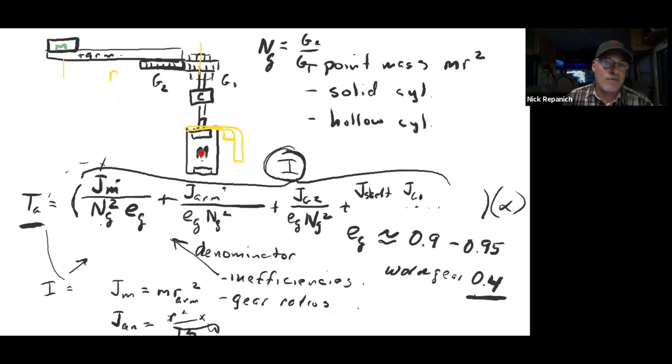They're all direct drive terms. That's nice for your formula, but that's actually bad for the motor, the overall system, because these things got reduced by the gear ratio squared. These are direct inertias to the motor and have to be turned. Those are the hardest inertias probably to turn. I'll bet you in the whole system, if I had to guess, that gear is your highest inertia value when you went to plug in numbers.